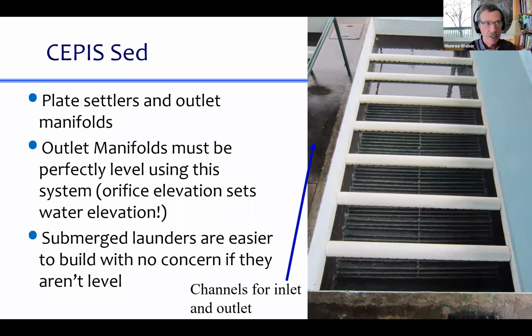So we get around that problem of having to have precisely installed manifolds by having the entire manifold submerged, and then the pipe is full of water. Our manifold or our launder is actually full of water as well, and so it doesn't matter if it's sloped or not.